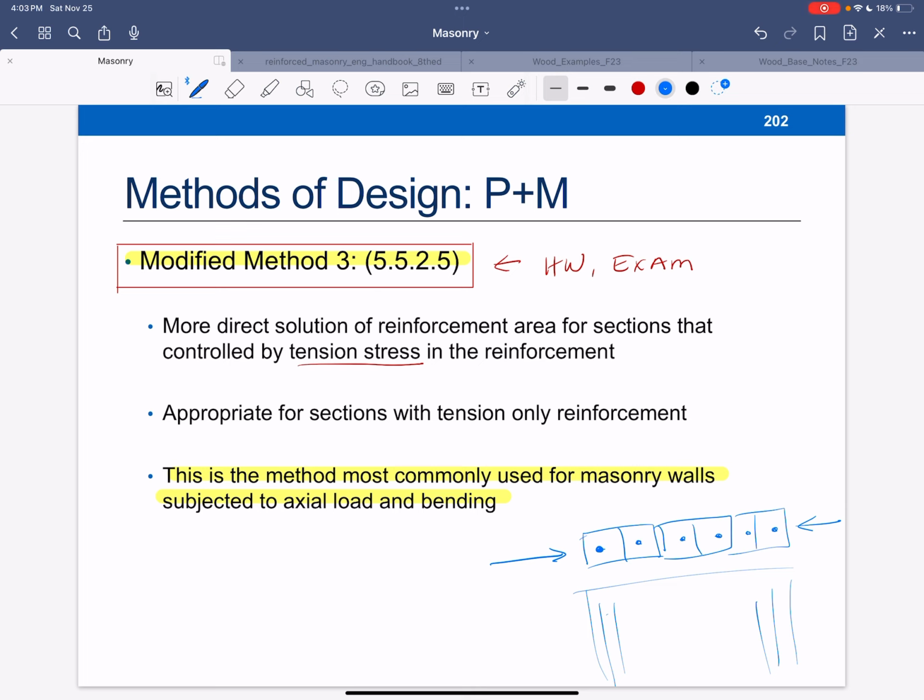What will happen if I want loads in this direction? It's the same type of thing, because I've got the same case where I'd like to have them closer to the tensile face if it's coming here and closer to the tensile face here, but we know there's only the hollow cavity. So most of the time I'm going to put it right in the middle and just do that all along the length. Obviously, it wouldn't necessarily be in every cavity.